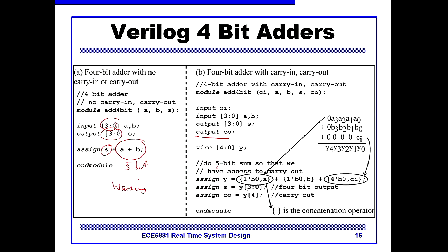It looks quite clumsy here because we need to do 5-bit adds with 0 in the top bit, because if we did this any other way, then the carry would get ignored. When you add 3 things together, you need to be mindful of the bits propagating through to the output.